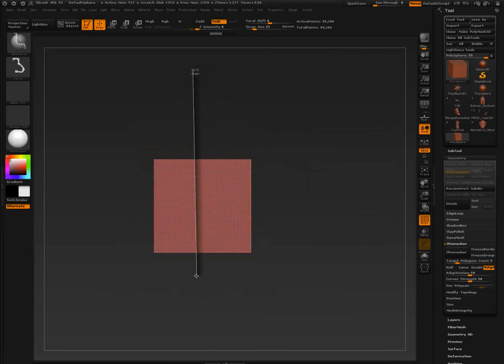The reason why we've done this is I want you to be able to free up that left hand, or right hand if you're a lefty. Hold the space bar and I can move the curve around, right? If I tap the Alt key, we can put a nice little bend in it. If I double tap the Alt key, we can make hard curves. So again, if I hold down the Control-Shift key, all I have to do is click on the document.